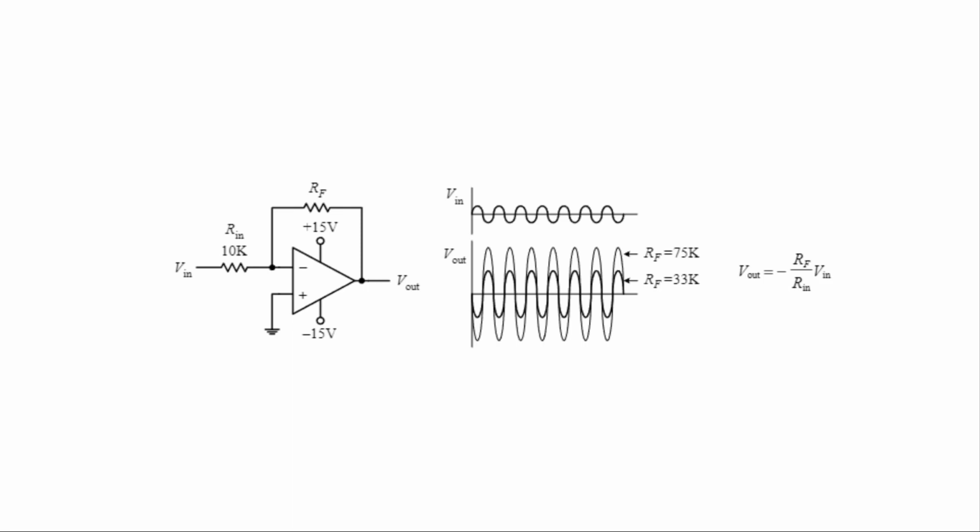Now there's also positive feedback, where the output is connected to the non-inverting input, and positive feedback has the opposite effect and drives the op-amp harder in either direction. Positive feedback is rarely used though. It finds special applications in certain comparator circuits.